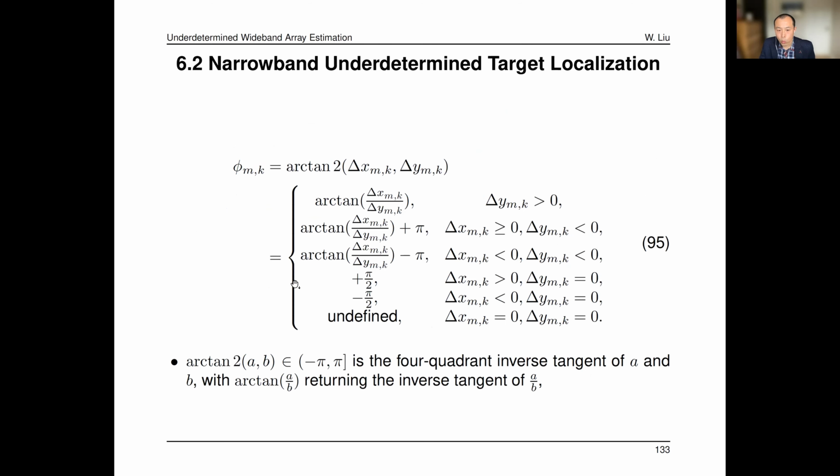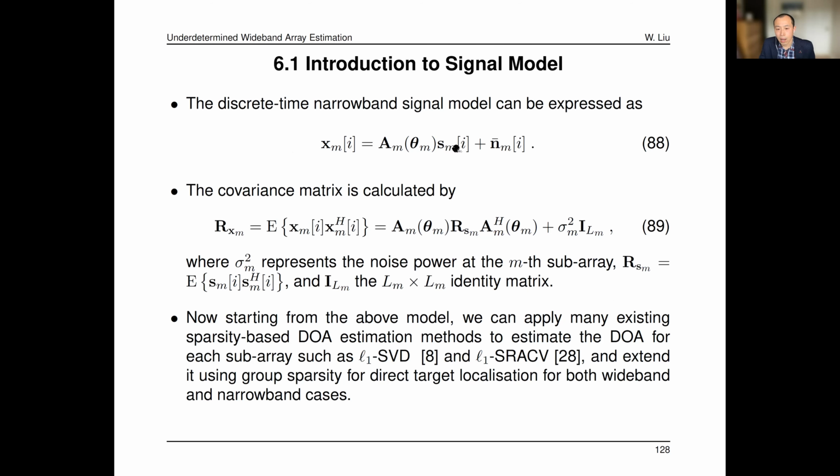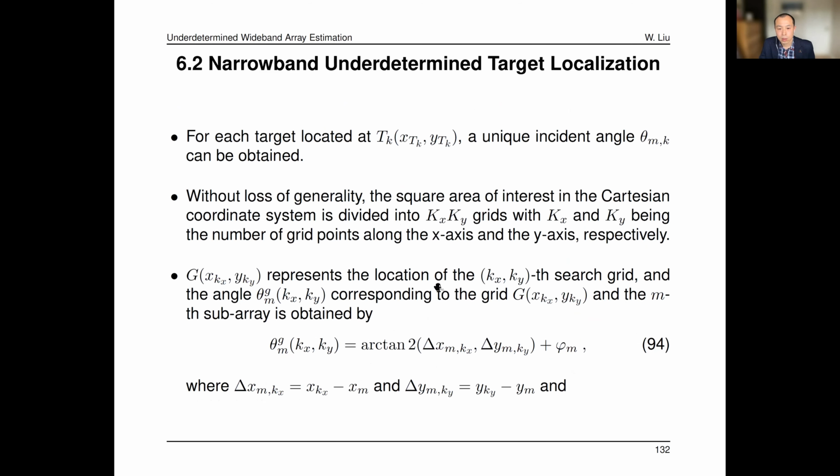That's an advantage, because here, when you form this group sparsity, this source signal for different subarrays can be different. So this M is dependent on the subarray. So you can have the same signal S, or you can have different signals S_mi. Here we have a general one, S_mi. So that's the big advantage. Different subarrays can receive different signals at different frequencies, and with different channel conditions. You don't need to have a synchronized distributed array system. They don't need to be calibrated. Individually certainly they need to be calibrated, but not the whole distributed array system.